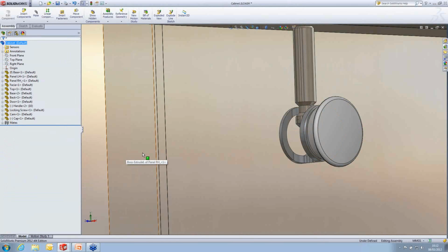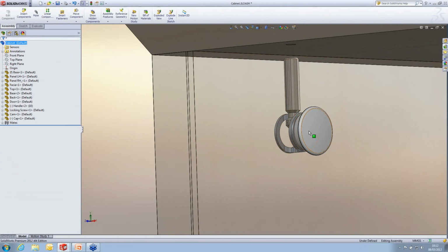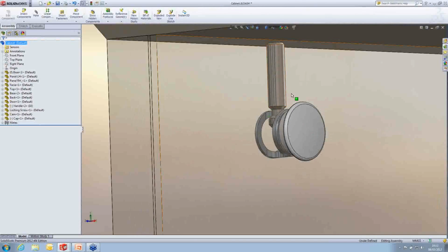That actually now leaves me in a position where I've fully mated up these components, and you may wonder why I've done it in this order. I've actually put the items in before I've actually got holes to put them into within this side panel, and that's so that when I put in the holes I can relate them back to these components, so that the smart component that I'm building will be fully contained. All the references will be contained to the components within the group.